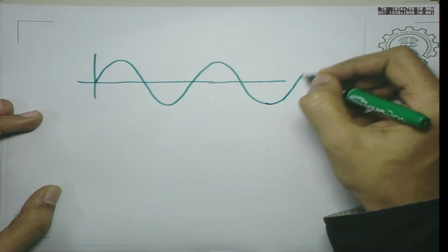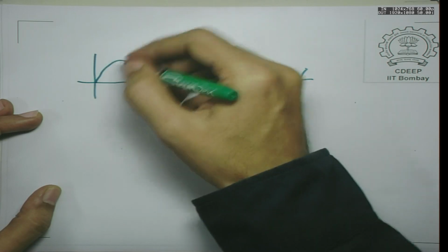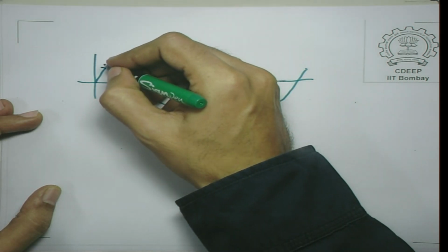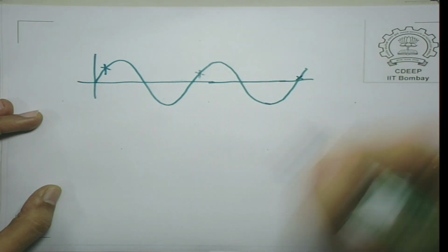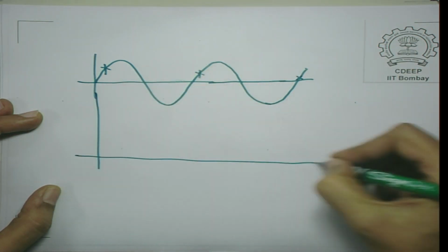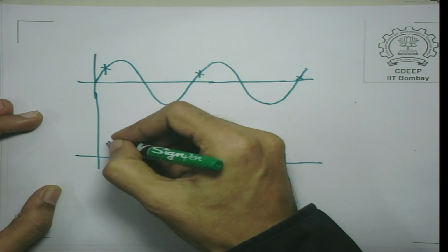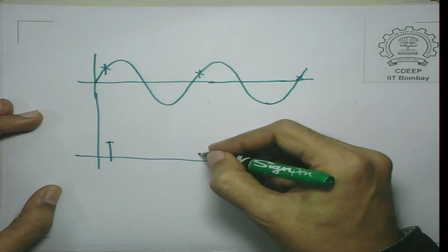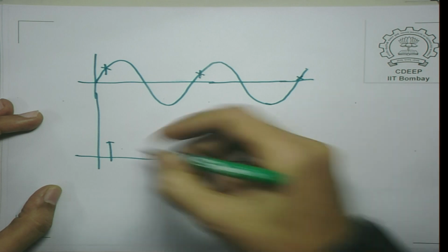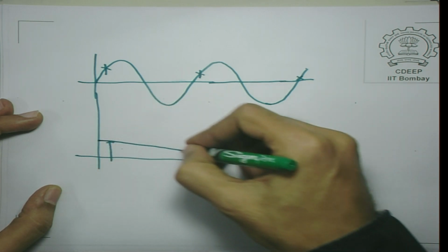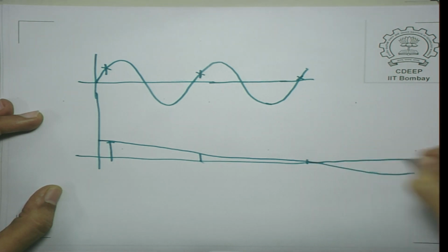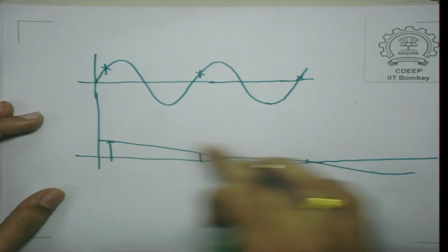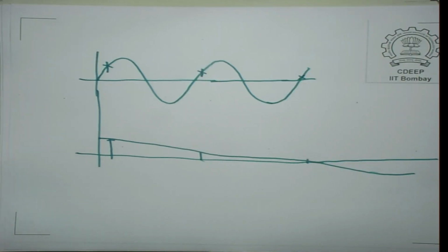a certain frequency, but your device is only measuring it at instants, you are getting samples of this waveform only at these instants. So, you are getting this value here, this value here and this value here, and if you interpolate between them, that is what you do while plotting, you will get a spurious inference that this is in fact a sinusoid of much lower frequency. This effect is called aliasing.